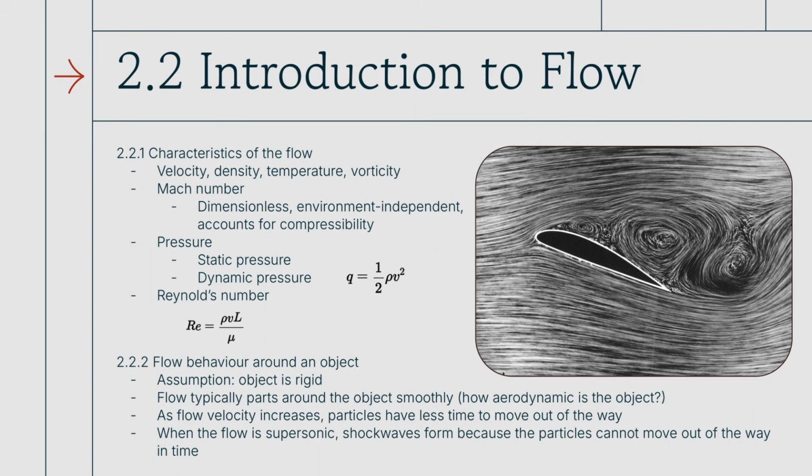You can also talk about pressure, as in the static pressure of a fluid. For example, there is a pressure in this room, but the air in this room is not moving, so it's just a static pressure. However, when the flow is actually moving, then you can talk about dynamic pressure. If you've watched any rocket launch, they will announce max Q. They're referring to the maximum dynamic pressure on the vehicle.